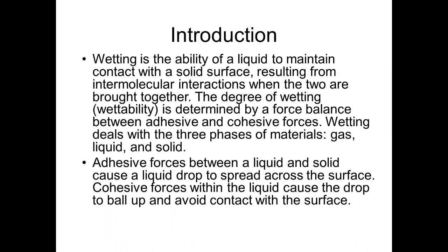Wetting is the ability of a liquid to maintain contact with a solid surface, resulting from intermolecular interactions when the two are brought together. The degree of wetting, which we'll define as wettability, is determined by a force balance between adhesive and cohesive forces. Wetting deals with 3 phases of matter: gas, liquid, and solid. Adhesive forces between a liquid and solid can cause a liquid drop to spread across the surface. Cohesive forces within a liquid can cause the drop to ball up and avoid contact with the surface. So that's the one we're going to look at for the most part in this presentation.